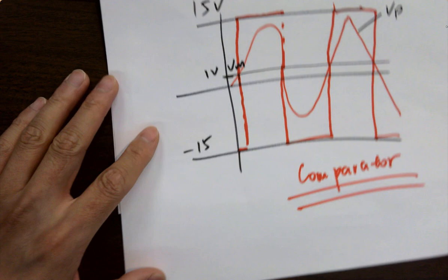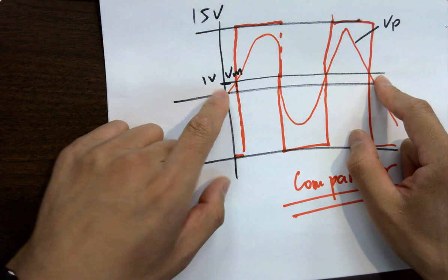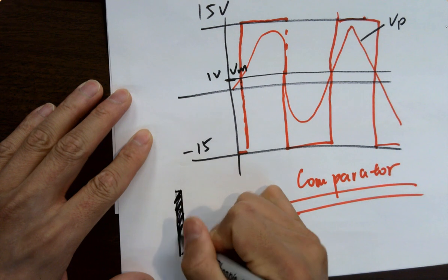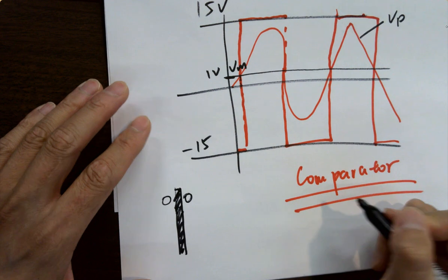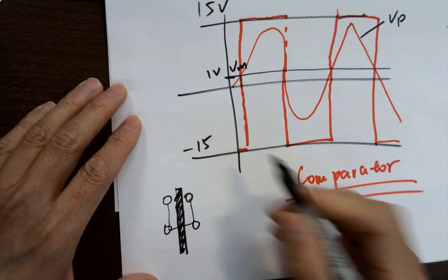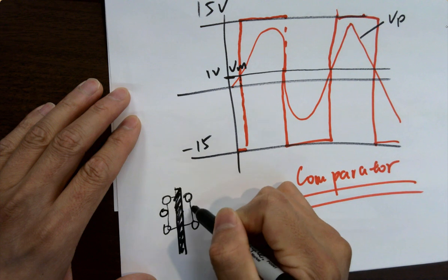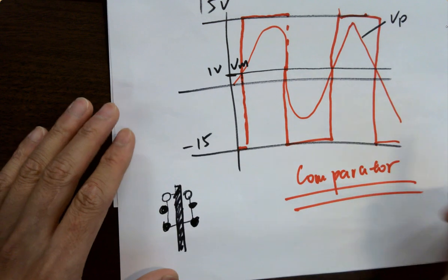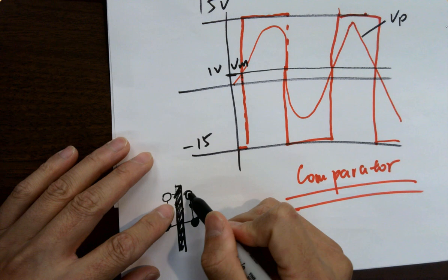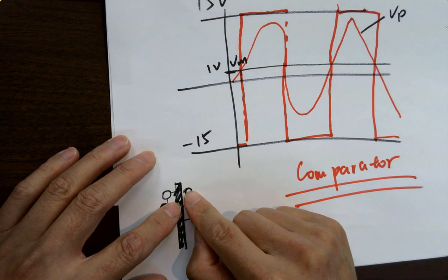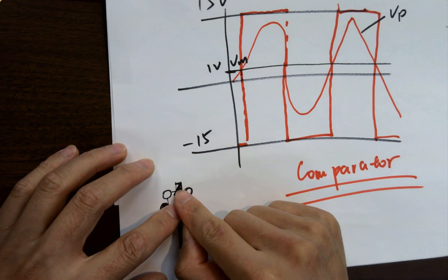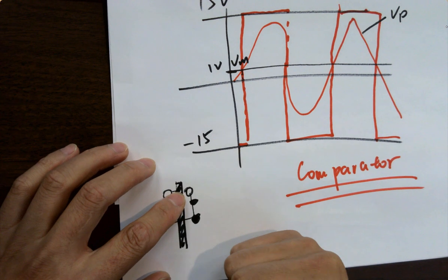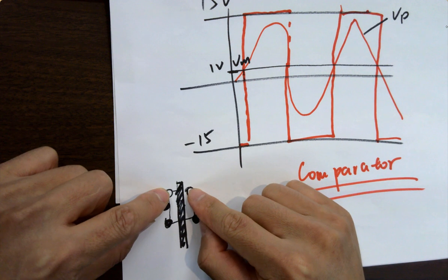What's happening is I set a reference signal for the two wheels of the robot. Let's just see. Here's a black track, right? And I got two sensors over here, right? And here's a car. The sensors are over here, and these are the four wheels. These are the sensors, okay? Whenever the sensor here is out of track, for example, this sensor gets on top of this black tape, the light is absorbed, so it's not receiving a reflection. So the signal being received here and here will be different.